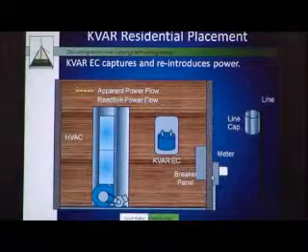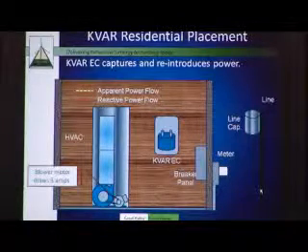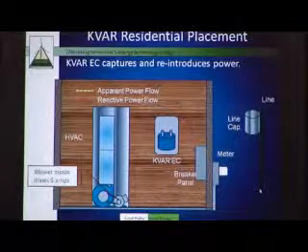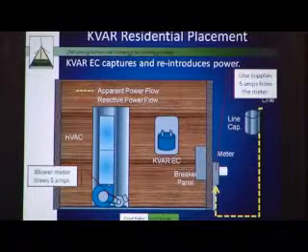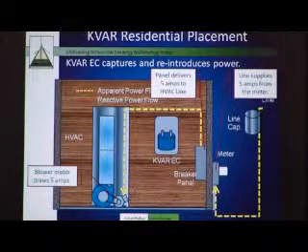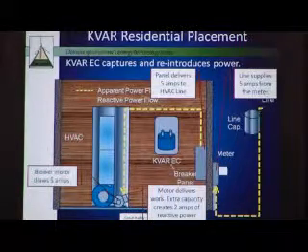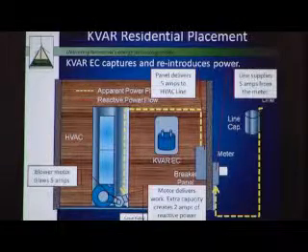Now let's look at a system where we have a KVAR installed. Again, the same basic setup. My air conditioner comes on, I've got a 5 amp draw. So I'm fed 5 amps through my meter, through the breaker box where I've distributed the power. And again, the motor consumes actually 3 amps and generates 2 amps worth of reactive power.